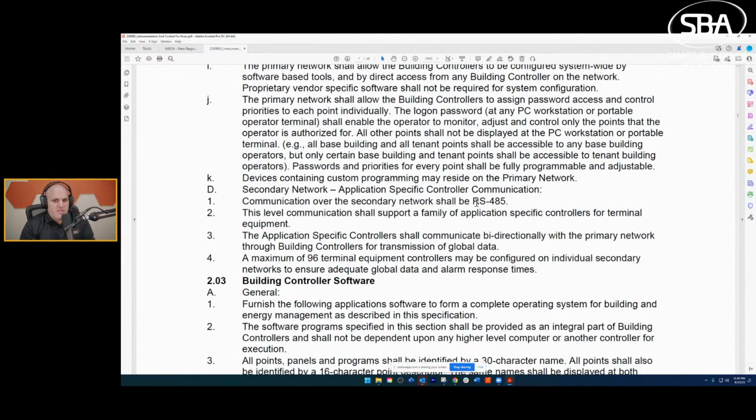That's your terminal units. Remember, we saw that in section 1. And they don't catch that it's RS-485. What's RS-485? If you listened on Monday, you know that that is the wiring and communication standard on which BACnet MSTP and Modbus RTU are built. This is BACnet MSTP.